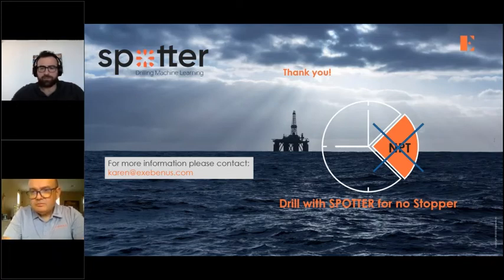The first question from the audience is, are you just using surface data for your model, or do you have to input other aspects such as details about the BHAs, that's the bottom hole assemblies, well architecture, hole size, casing info, or mud characteristics? We use standard surface drilling data, which I mentioned earlier in the talk. We also use the mud density, but this can either be streamed or not present. We have sensible defaults which will work, and users are able to set it as they need to if this parameter is not being streamed.